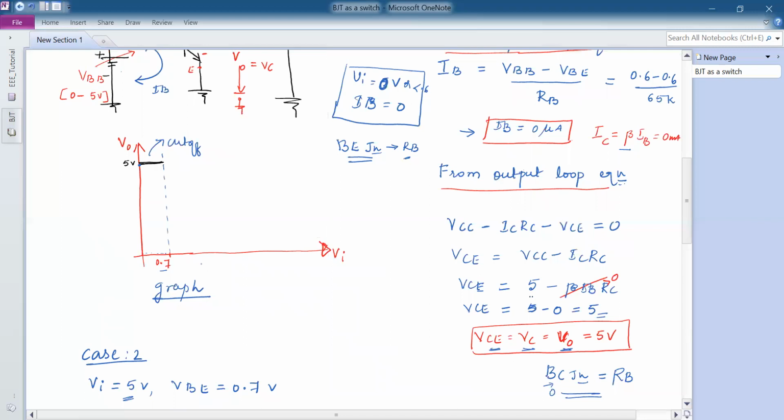As the input is varied beyond 0.7, you should get a decrease in the V0. So it is slowly decreasing. And now, since the transistor has entered into saturation, you know that in saturation, IC current is always varying very slowly. So even the output varies very slowly when the transistor enters saturation, as Vi is greater than 0.7 and above.